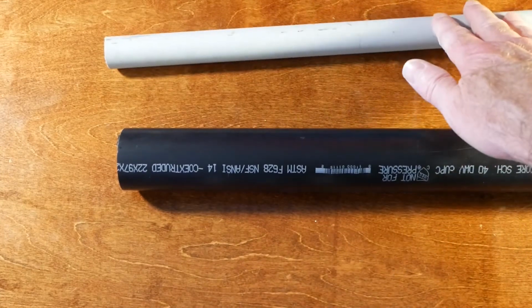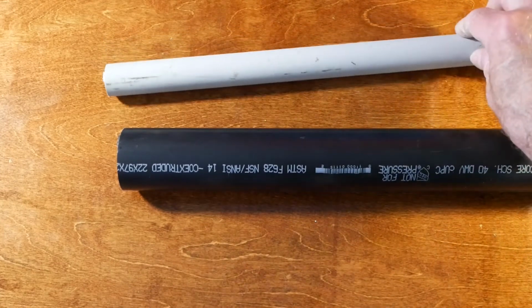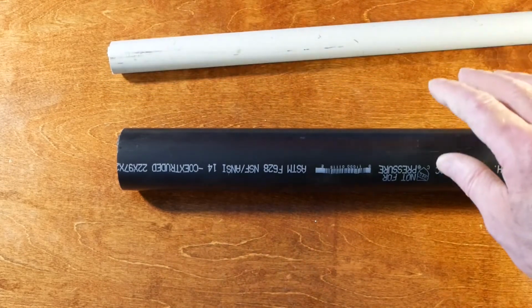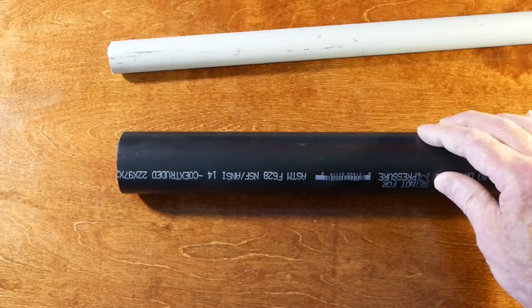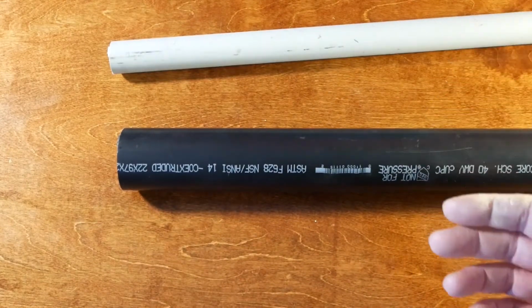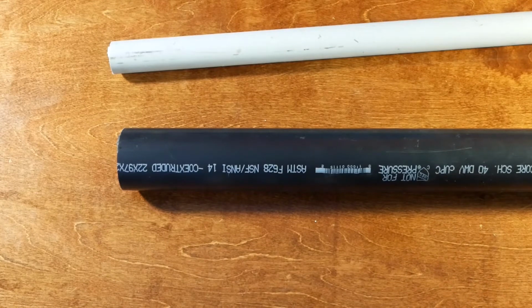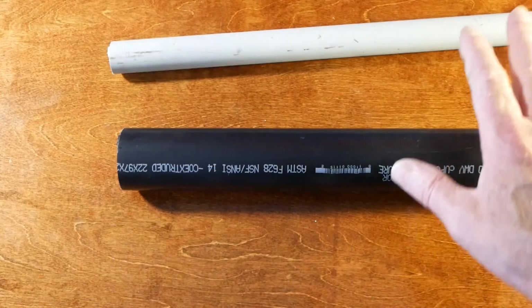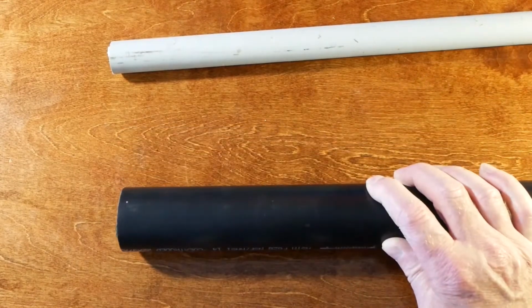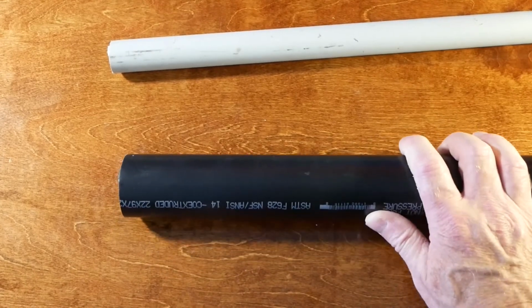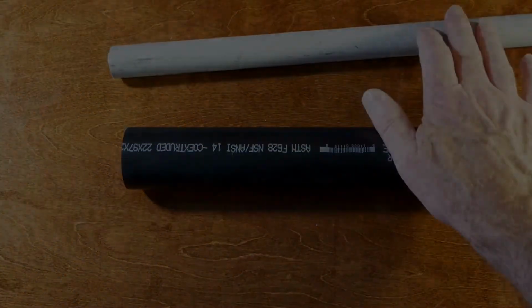We can increase the pressure. If we increase the pressure enough on the smaller diameter pipe, we'll increase the flow rate through that pipe, and at some point we can equal the amount of volume of water that's coming out of the larger pipe. So the analogy in this case is pressure is voltage. If we have more voltage in a system, we're able to force more electrons through that circuit, and we can actually equal the current flow in a circuit that has much less voltage. In this case, our analogy for this is our 6 volt system. Our analogy for this is our 12 volt system.